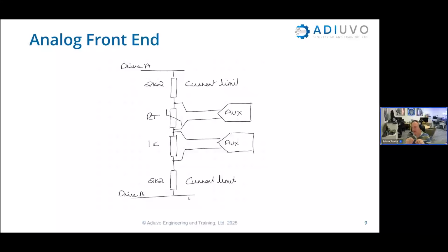In this, we're going to take this into the auxiliary channels of the XADC. The XADC has a dedicated VP-VM pair, and then it has 16 other auxiliary inputs. The only difference is the auxiliary ones are not dedicated, they're shared with digital I/O, so they have a slightly lower bandwidth that they can sample signals at.